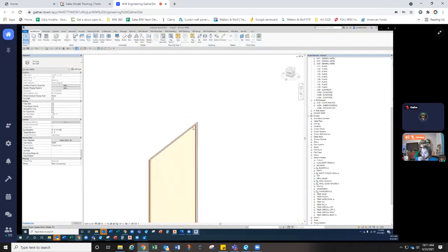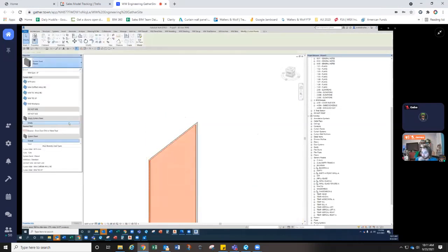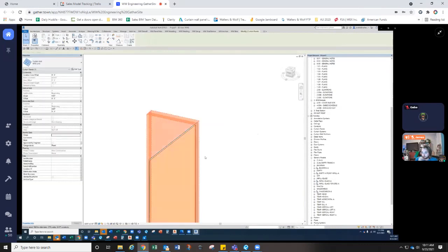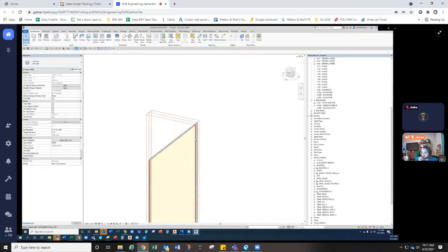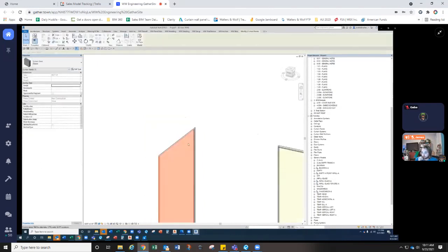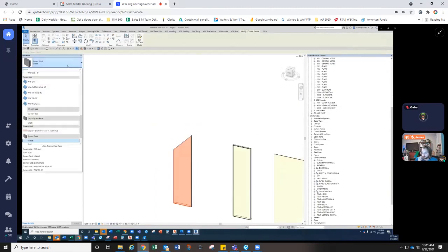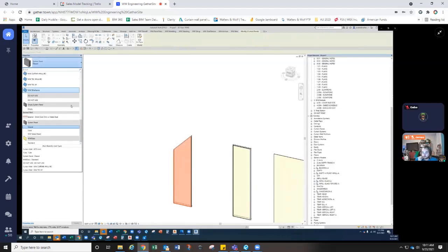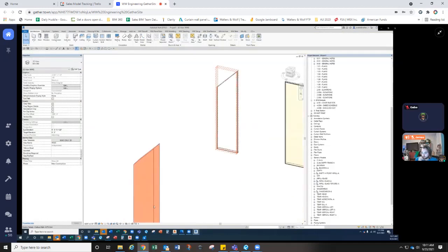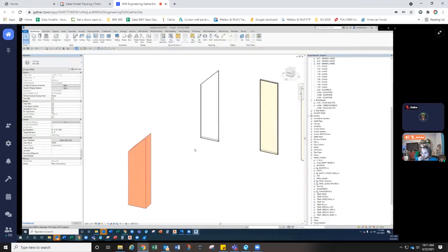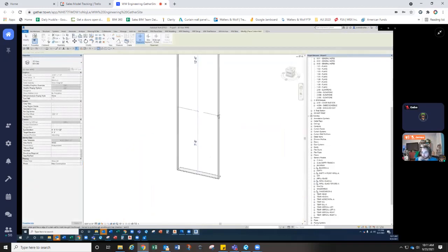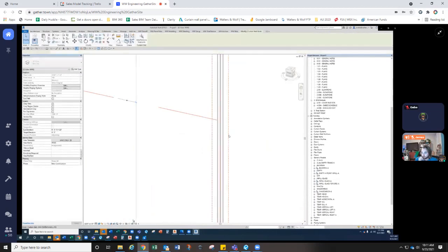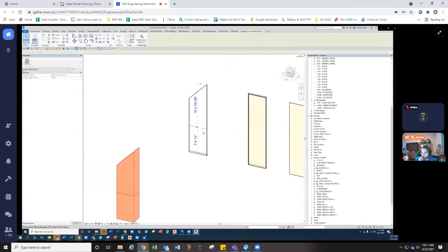Then I would tab into my curtain panel and switch it out for a W75 unit. So we're actually nesting within the wall. And then I would once again grab my curtain panel. What we've discovered as an easier way to place these is to switch it to what we're calling WW raked panel. And this pops the panel way out here. I'll show you why this helps in a moment. But then I take my curtain grid and I lay it in here. The reason why I'm putting this curtain grid in is because this is actually going to be controlling the height of the horizontal.